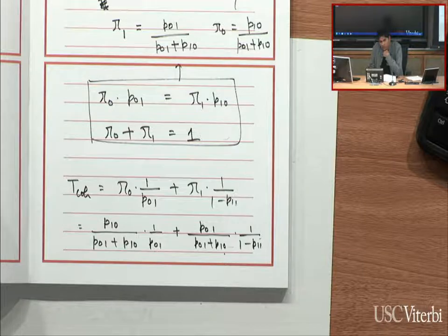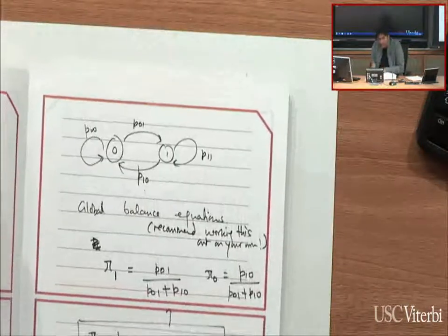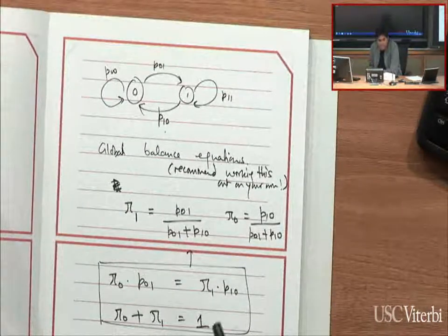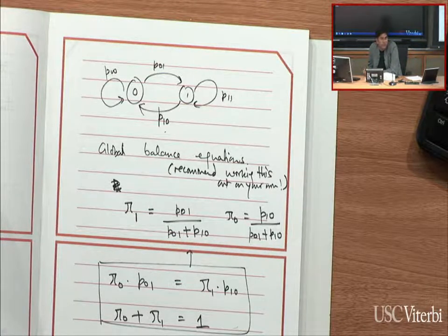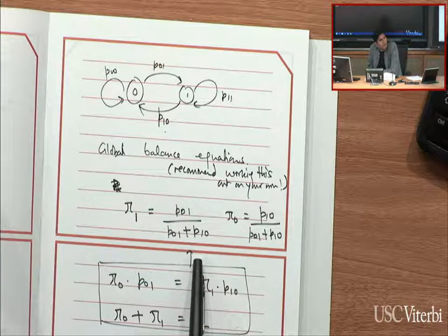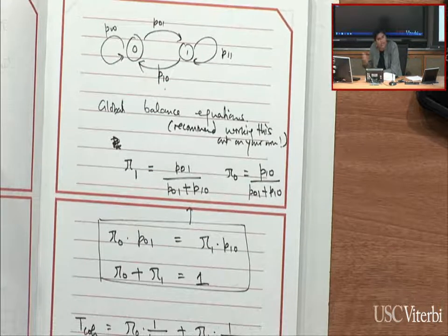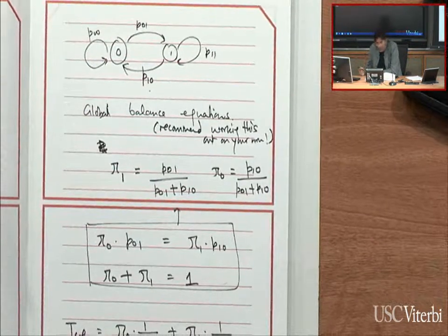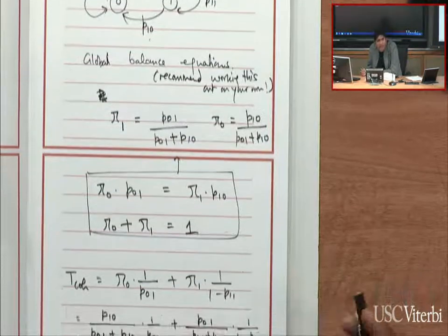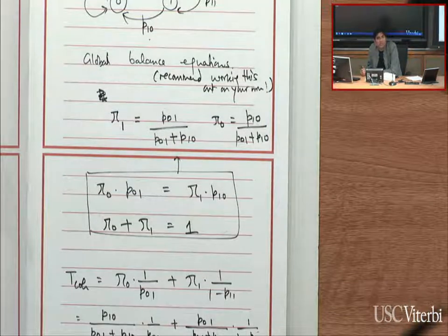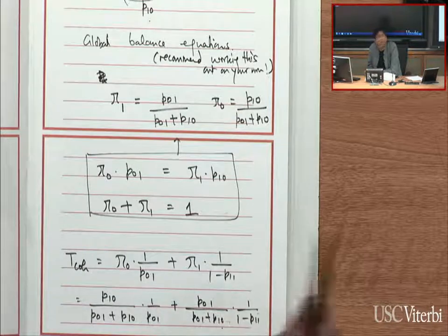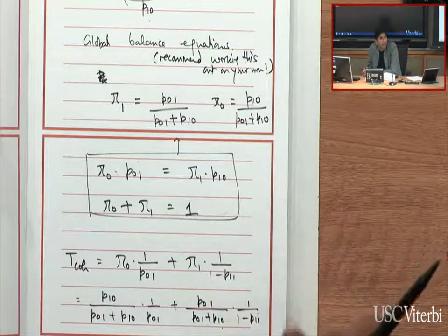So what good is this model? One thing we can do with it is we can capture what we actually observe in the real world. We can see how frequently you see a good channel going bad, how frequently you see a bad channel becoming good, and use them to infer these two numbers. And from those numbers, you can now simulate that environment. But besides simulating the environment, you can also do prediction. So you can ask questions like, if I'm now in a bad state, how long will it take for me to become a good link?